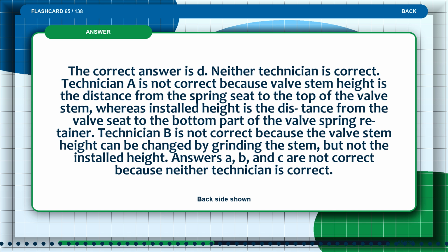Technician B is not correct because the valve stem height can be changed by grinding the stem, but not the installed height. Answers A, B, and C are not correct because neither technician is correct.